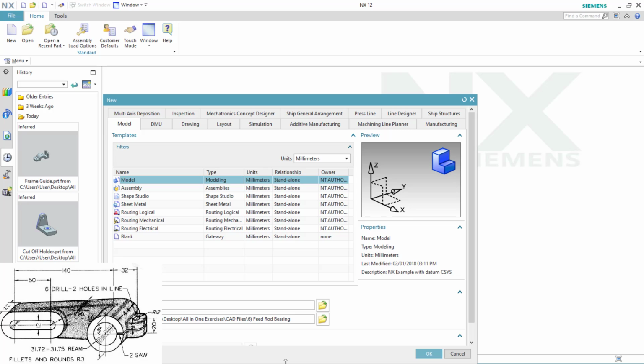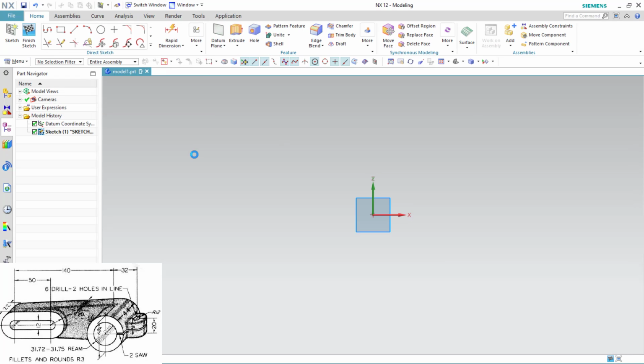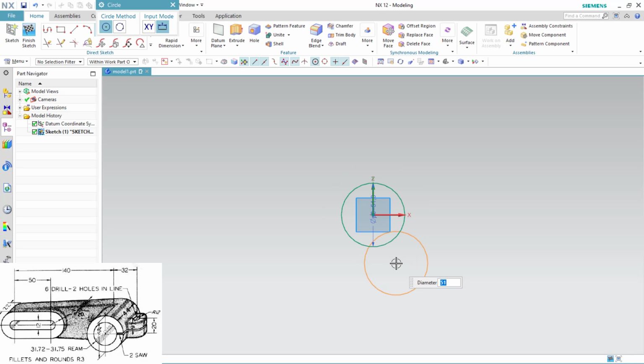Yeah, this one. So start with the front plane. If I consider the first angle projection, so I can select the ZX plane here for your reference. It will not confuse you. Okay, so first thing, I'll draw the rough sketch. So I'll start with the center. The values you can see here. Yeah, diameter is 51, so inside is given 31.7.